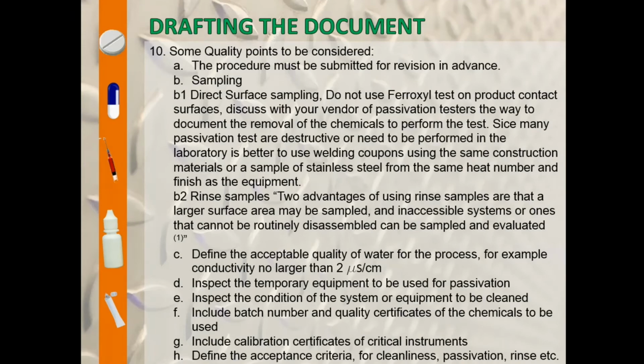The higher the quality of the water, the higher the level of cleanliness that we can achieve. We can say that conductivity must be under 2 microsiemens per centimeter, or use purified water or water for injection as per pharmacopoeia.